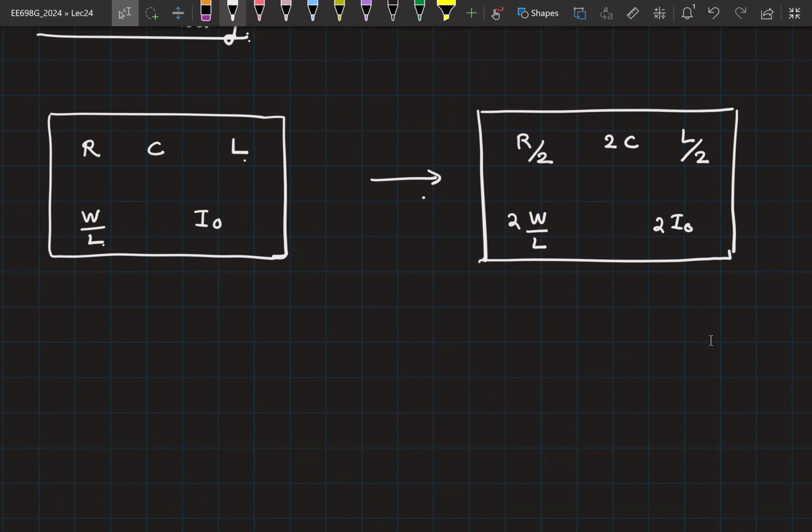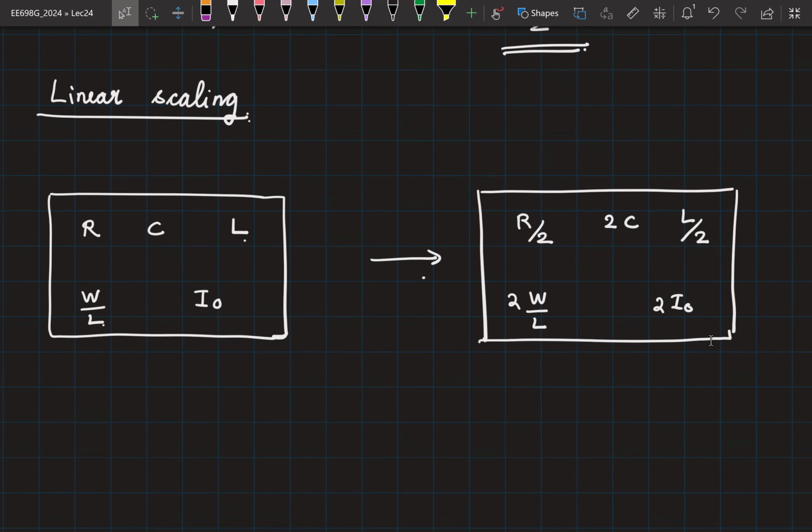Right. Okay. So if you have designed an oscillator, you find that its phase noise is higher than what you require. And if it's last minute, one thing that you can always blindly do is increase the power consumption. Do linear scaling, all the other parameters remain as it is, and you get a reduction in phase noise. Now, let me also show a very, very intuitive way of understanding how to relate the noise between a delay line and that of an oscillator.